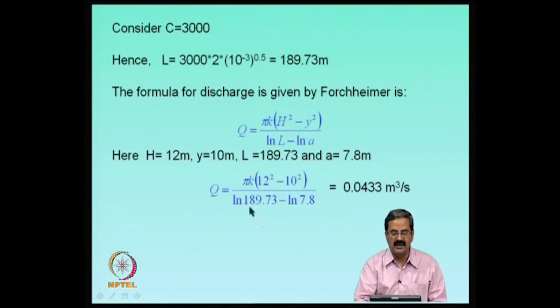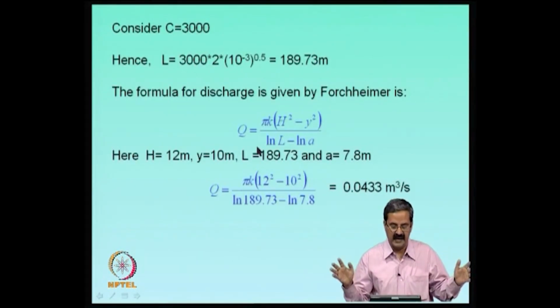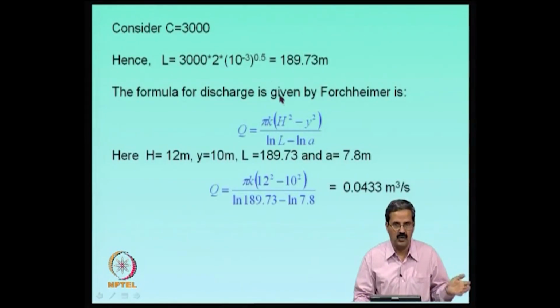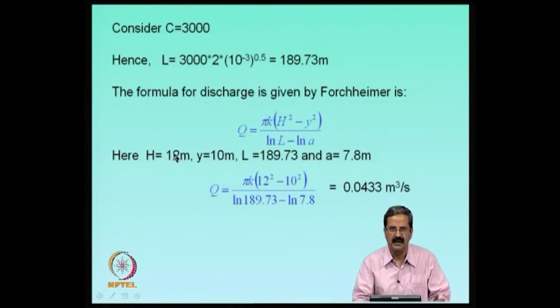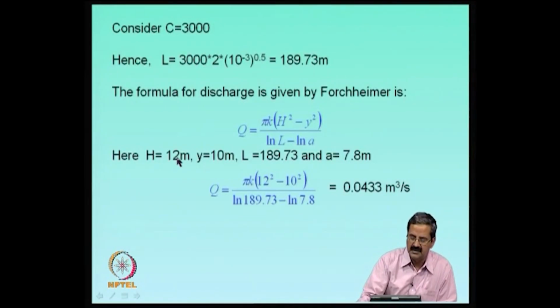So, this is the discharge that the area has, the total amount of water that should be thrown out, to see that the water table doesn't affect the construction of the foundation at the 10 meters level, and then we are trying to go at least 2 meters down from that. This is just an example; numbers in field applications could be different, but I just want to give a flavor of what could be done here.